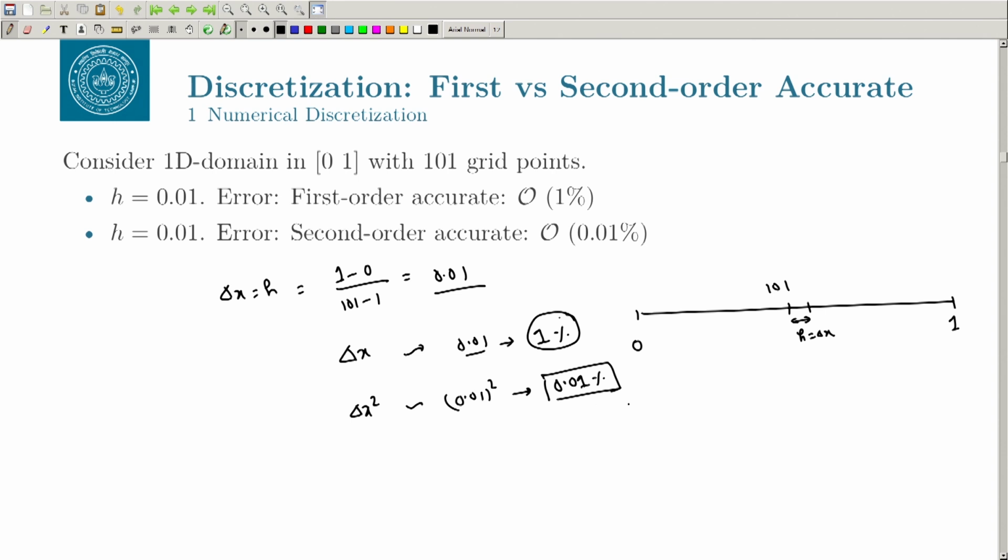So, you would be tempted to use central differencing everywhere, but let me bring some bad news: you cannot use central differencing directly in a convection problem. Why? Because accuracy is not everything, your scheme should be stable also, right.